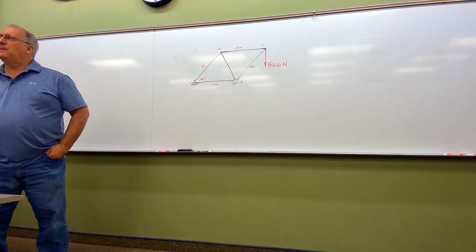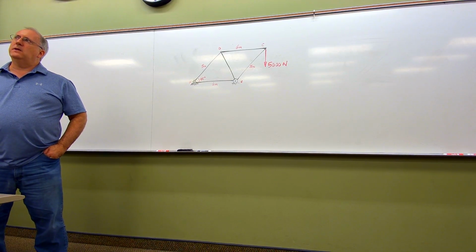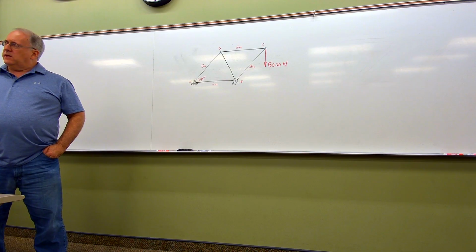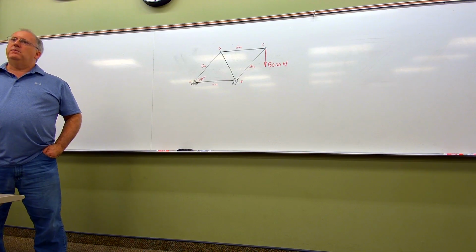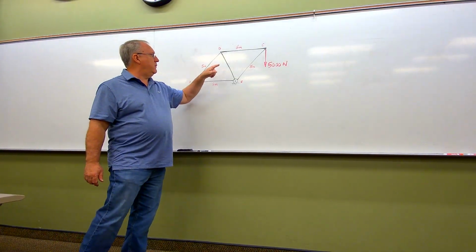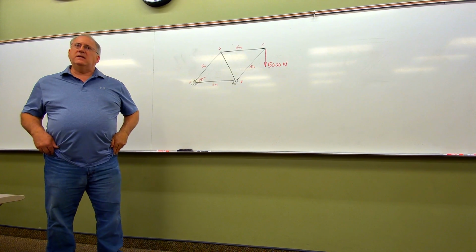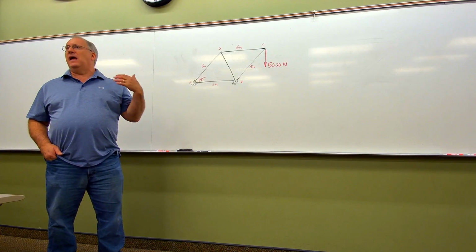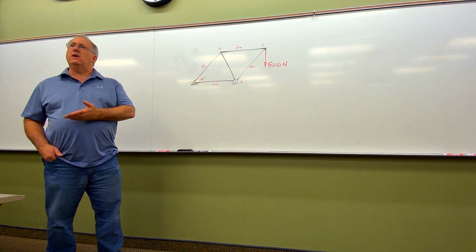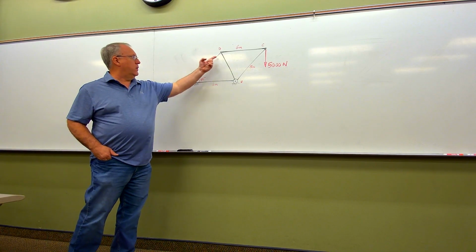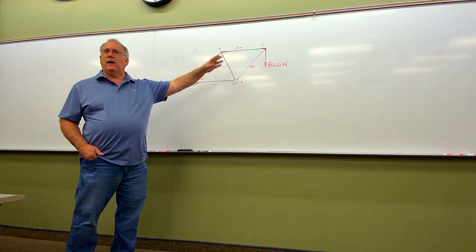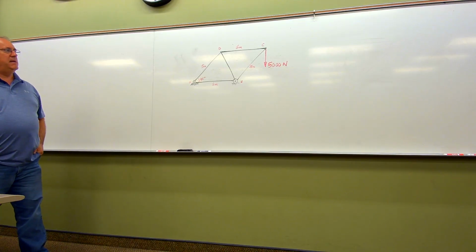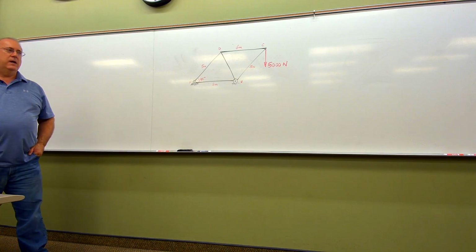Now, a moment ago, I commented on the idea that the method of sections can sometimes get us more directly to what we want than the method of joints. Here, in this particular problem, we're being asked to solve the forces in each and every one of these member forces. That type of ask usually lends itself well to the method of joints because it's designed to give us everything. Let's say, on the other hand, that the problem had merely said, I don't care about anything else, I just want to know what the force is in member AD, and you don't care about the rest of them. In a situation like that, the method of sections can get you more directly to that and maybe make it a little quicker, a little easier for you to figure that out. So that's the difference between the two.